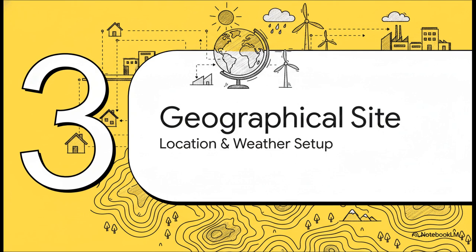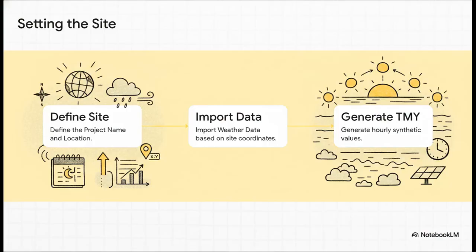Okay, Section 3, Setting the Geographical Site. This is where we breathe life into the simulation by pinning it to an actual spot on the map. You've got 3 sequential steps here. First up, define your project name and punch in the exact coordinates. Second, the software uses those coordinates to pull in the monthly weather data. And step 3 is absolutely crucial. You have to generate hourly synthetic values, often called a TMY. Since the sun moves and clouds roll by constantly, PVsyst needs that hour-by-hour breakdown to run its precise mathematical models for your site every single day of the year.